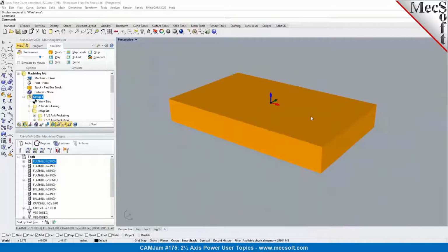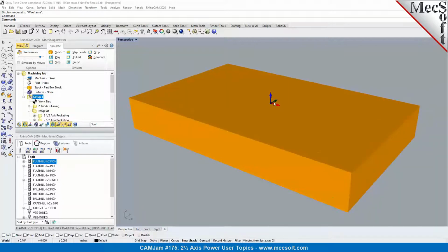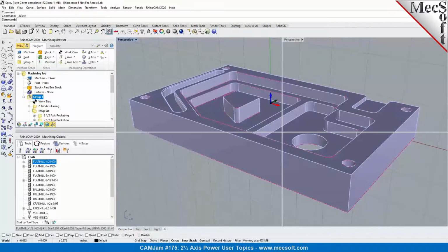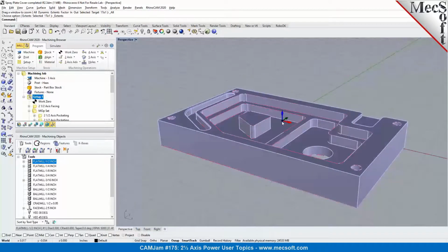In this particular example, you will notice that the World Coordinate System origin, also known as the WCS, and the machining coordinate origin are currently coincident. Which means when you first import your part or create your geometry in the CAD system, the CAD system origin is also, by default, the location of your XYZ0. In this model, this is where we have your XYZ origin.